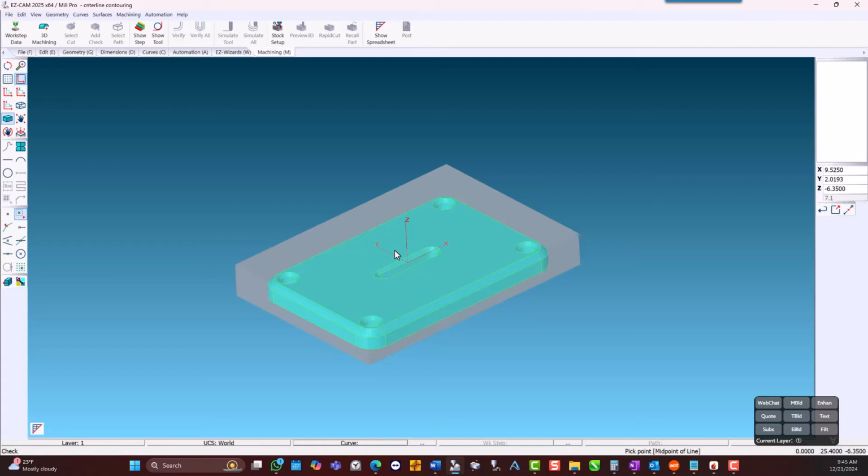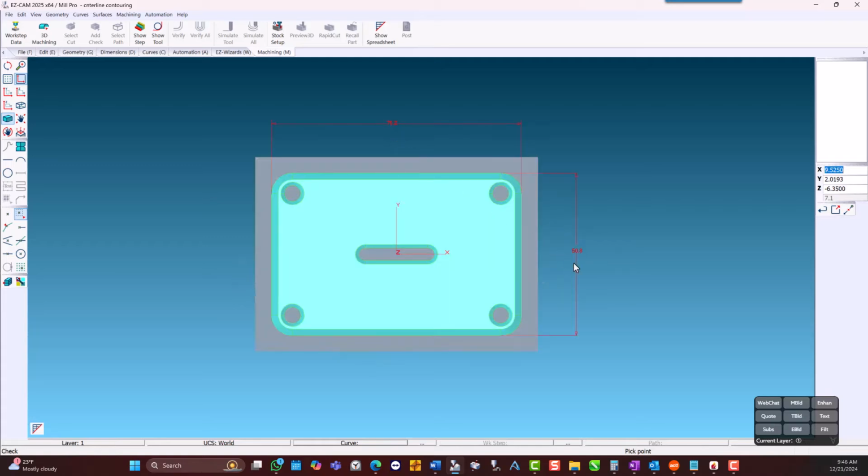Part 0 is below the surface of our stock, requiring a facing operation. Looking at the dimensions, the diameter of the tool will need to be about 60 mm for a single pass, left to right, or right to left if you change the cut angle to 180.